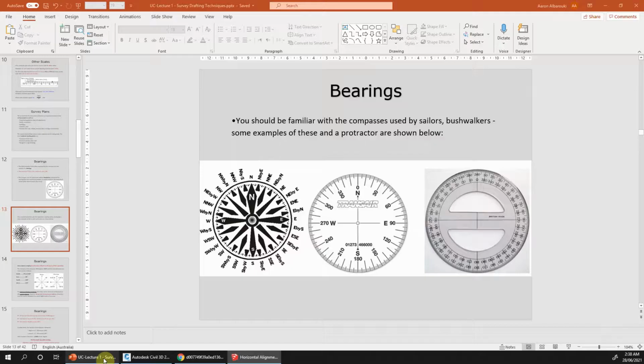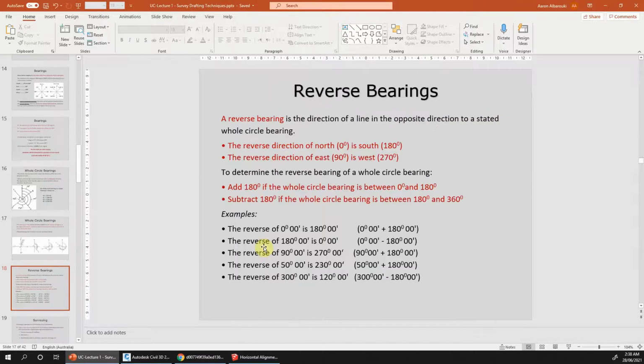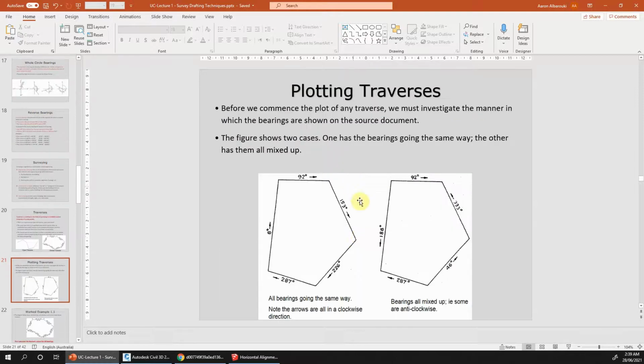But you'll learn in this lecture in a minute, after this one, that each 2 points connected together, for example, point 1 and 2, are connected with a segment, we call it. This segment has a length of 22.9 meters and a bearing of 45 degrees, 10 minutes and 30 seconds. Anyway, look, let's leave that to the side. I'll go through those in the next video. But the point is that this is important information that we have to learn so we'll be able to use them. You don't have to memorize them, but you have to understand them. This is the important part. Alright guys, I'll see you in the next video and we will continue from there.